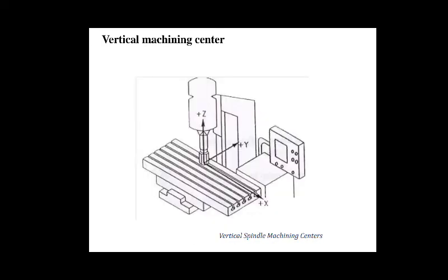With a vertical spindle, tools stick straight down from the tool holder and often cut across the top of a part. One disadvantage of vertical machining is that when tools cut across the top of the part, the metal shavings called chips often pile up around the tool and interfere with the cutting action.